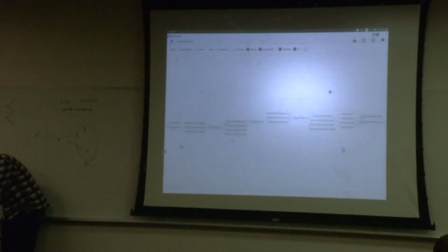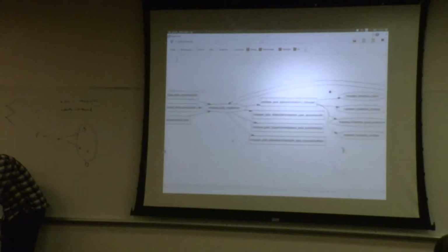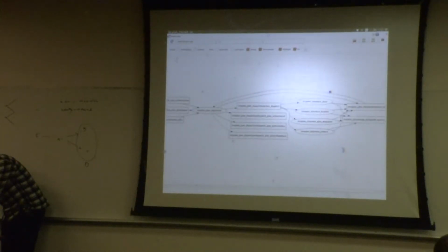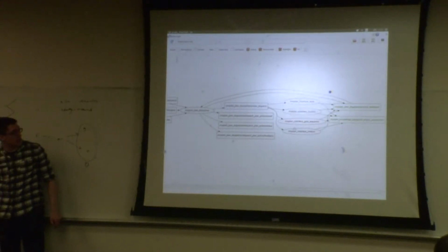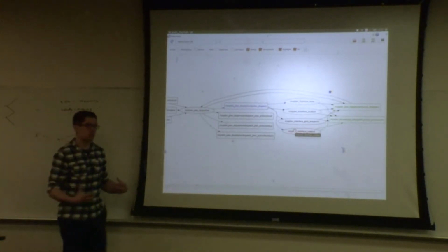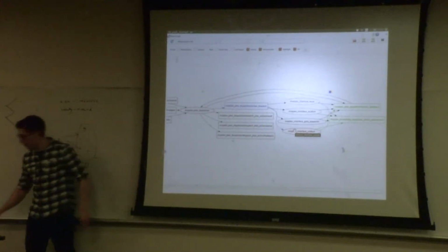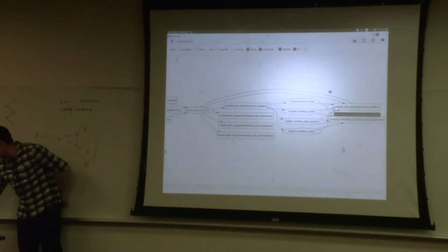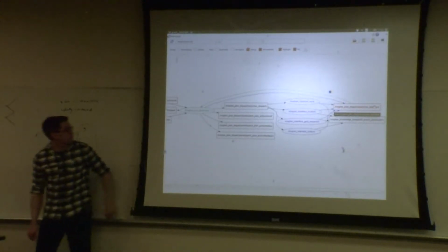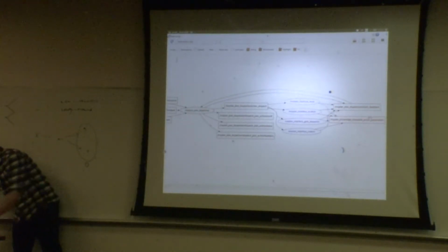Okay, so this is the same as before, the same chain of nodes, but now at the end on this dispatcher here, we have these 4 interfaces, and they're not publishing or calling the service of any actual lower level control. These are the simulated actions. So they'll go to sleep for some time, and then with a probability 100%, that's the parameter it's set, they'll publish on action feedback to the ROSPlan dispatcher that the action has been success. Okay.